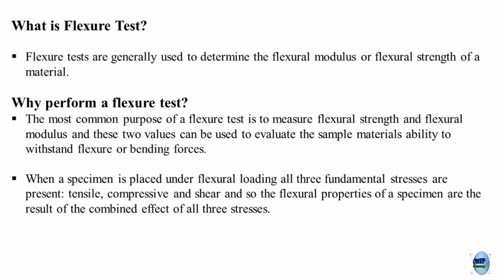The most common purpose of a flexure test is to measure the flexural strength and modulus, and use these values to evaluate the sample material's ability to withstand flexure or bending forces. Whenever a specimen is placed under flexural or transverse loading, there are three fundamental stresses present in the specimen: tensile, compressive and shear. The flexural properties of a specimen are the result of the combined effect of all three.